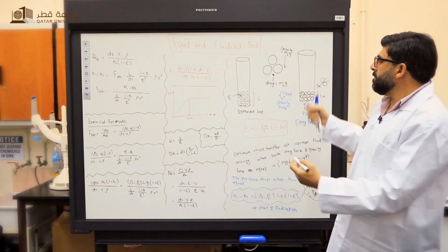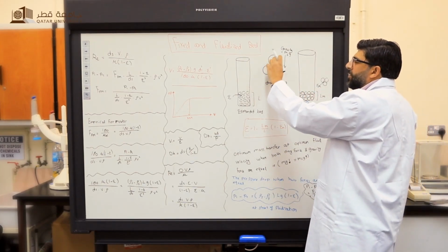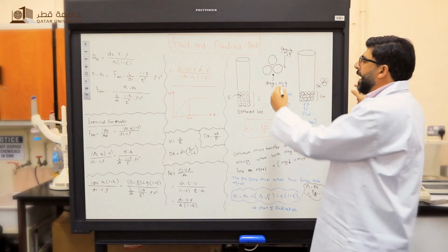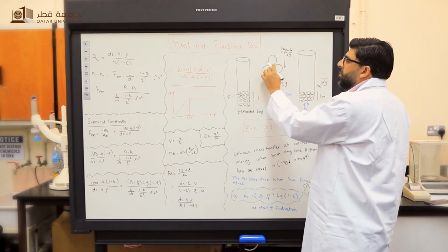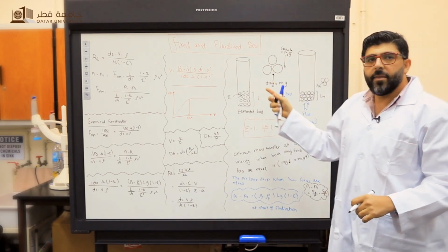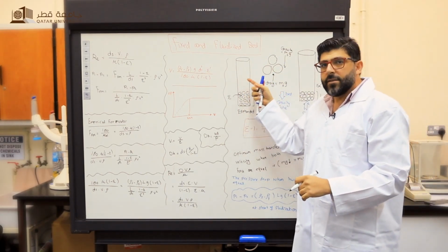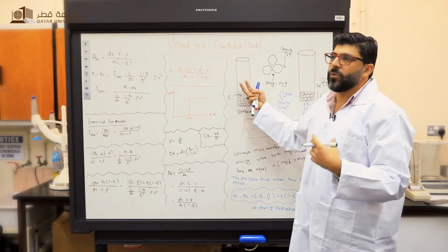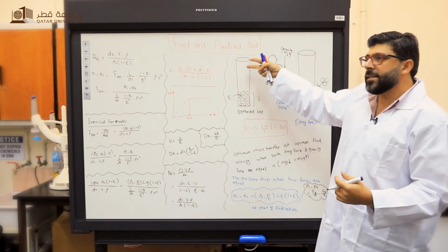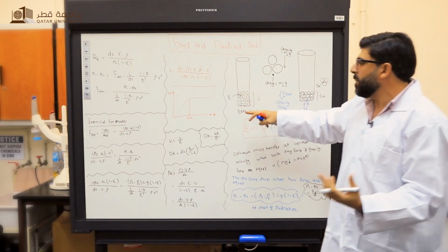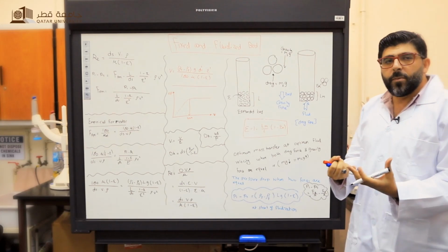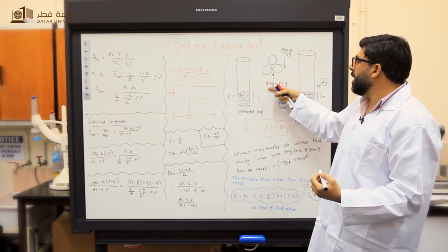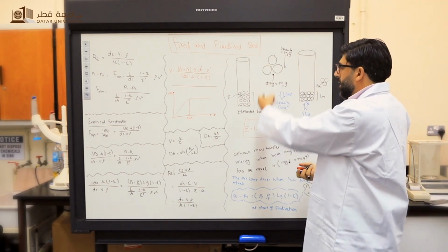Fixed means the particles are in contact with each other. There are no spaces between them. So when the gas flows, there's no reaction, because the gas can't cover these areas; they are compacted to each other. And if the drag force is much higher than the gravity force, these particles can get out of the column, and I also can't treat the gas itself, because the gas speed will be larger than the particle speed. So the optimum speed is when the two forces are equal: the drag force equals the gravity force.